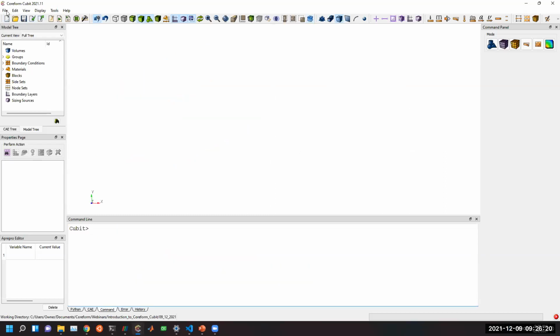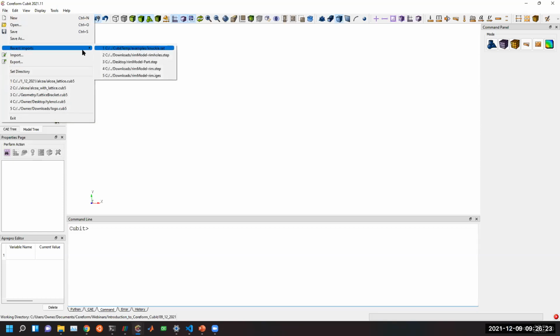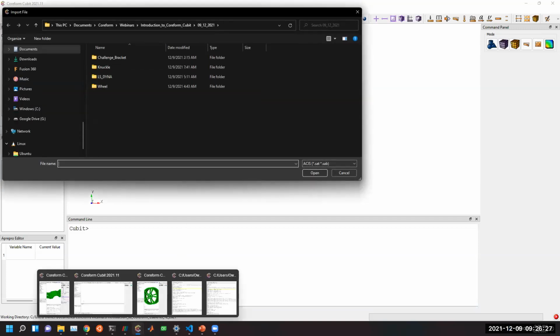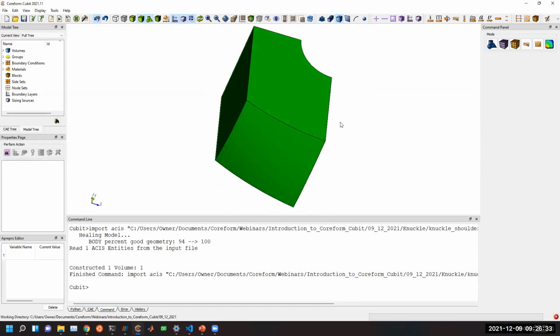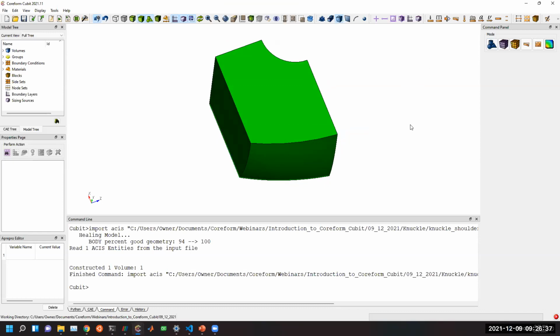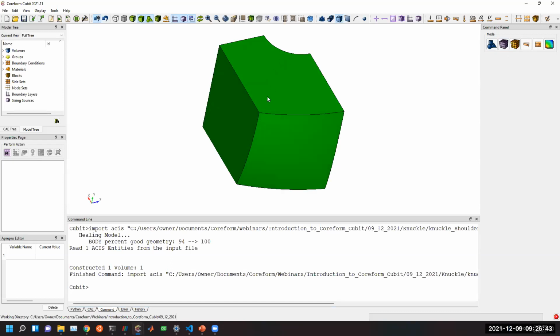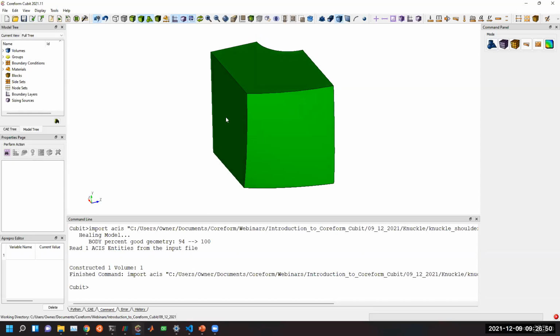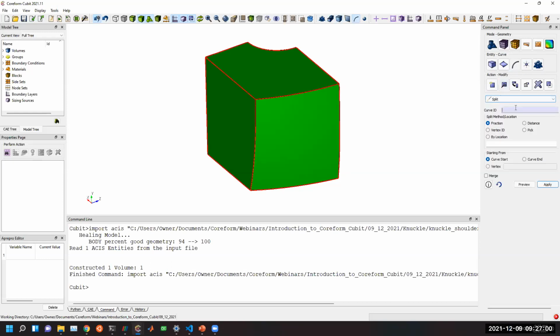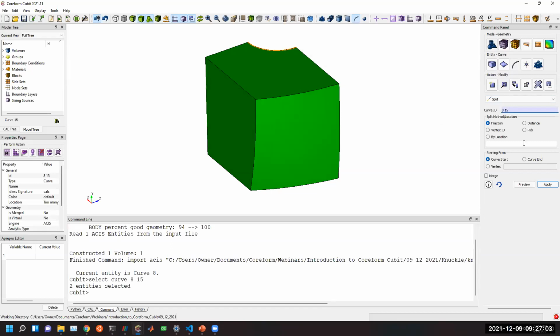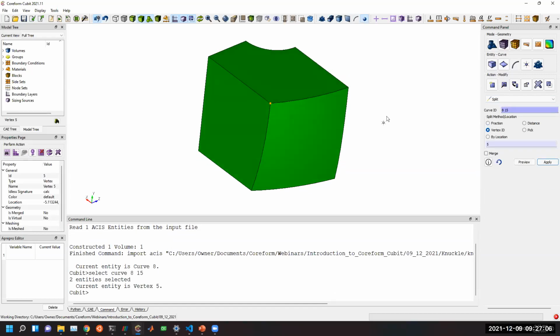Now, to address this shoulder creasing, let me go ahead and import just that shoulder. So I'll show this on just the shoulder by itself, a couple ways to get a crease there. One way is to partition the geometry, again, to have a cut here, because along a cut, we're going to have only C0, which is only continuous, not smooth. So to do this, what we might do is partition these curves, or split these curves by the point closest to this vertex.